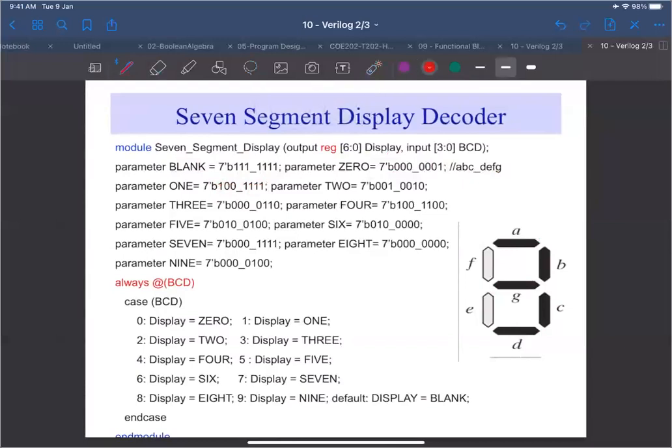And then you can also verify that each digit corresponds to its segments here. For example, let's take 7. 7 says that A, B, and C are on and the rest are off. So this is A, B, and C. This corresponds actually to 7. So it's just a matter of assigning which segment to display, which segment to turn on and which segment to turn off.